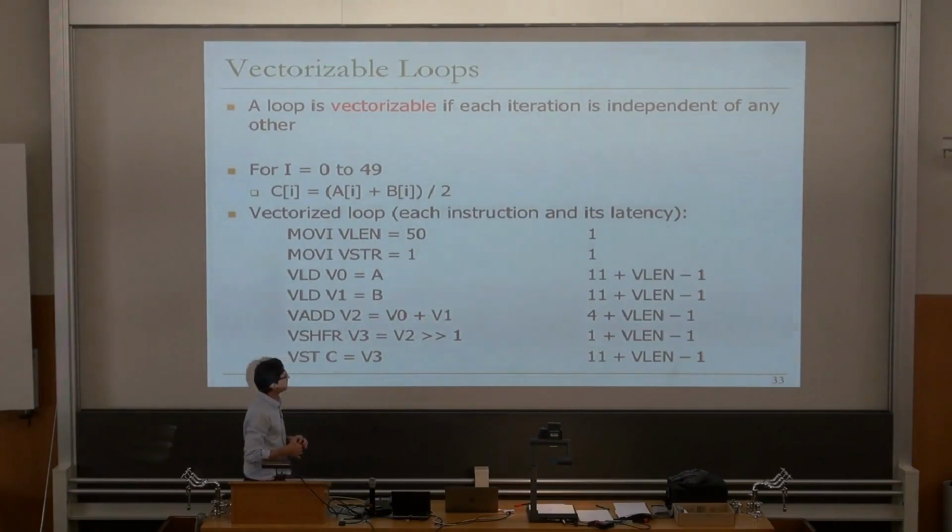So, this is the thing. The latency of the very first access to memory, same as the latency of the very first addition in your vector functional unit, you're going to see it completely because there is nothing else in the pipeline at that time, right?